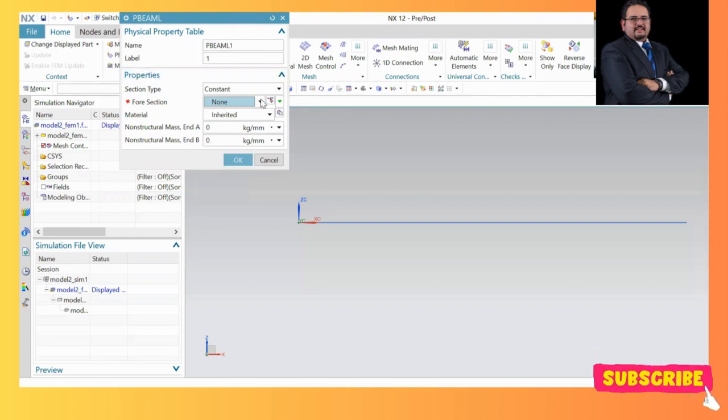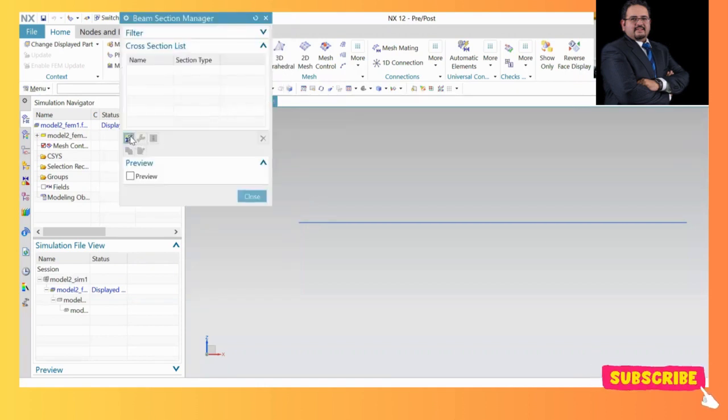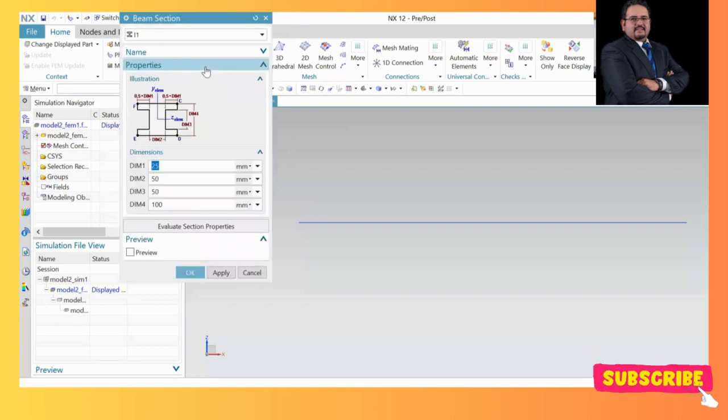Now students, this is a very interesting part here, because if I click on this small icon that says show section manager, and if I click create, by default it tells me it has many cross sections in it. So I can assign any cross section to the line that I have created, right?